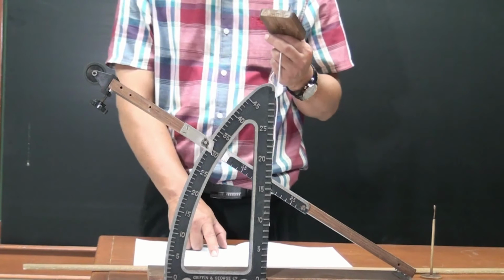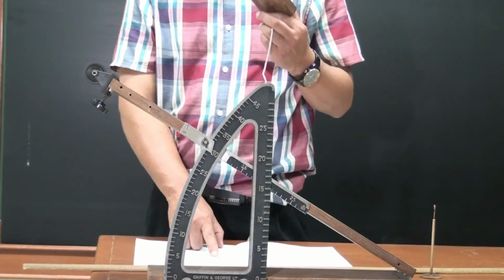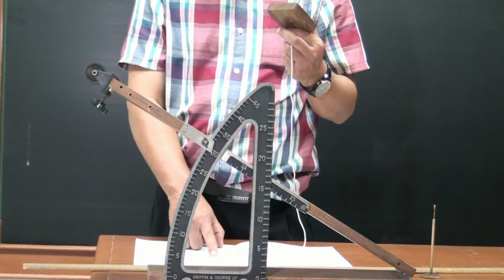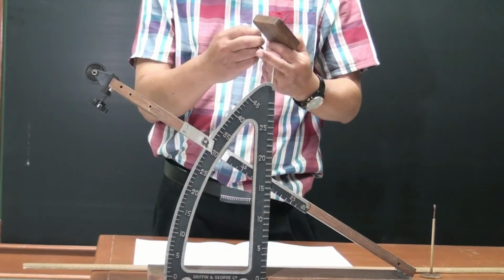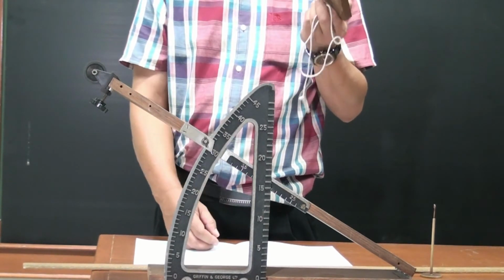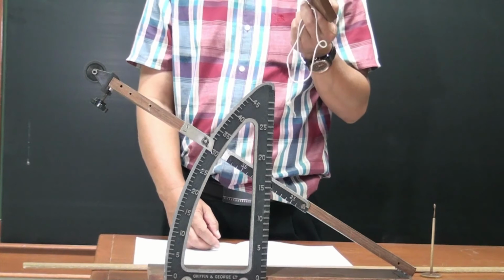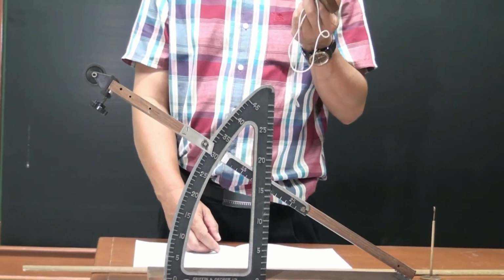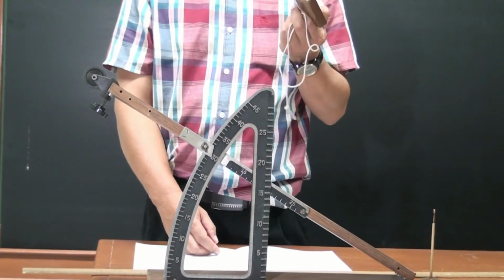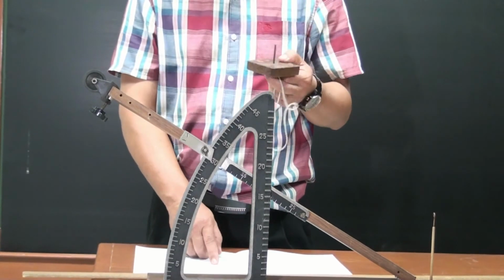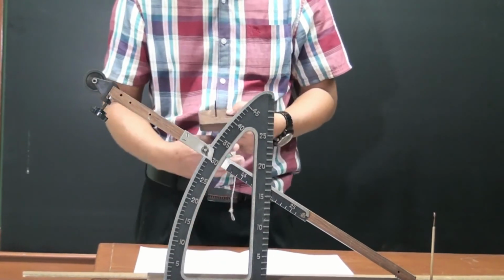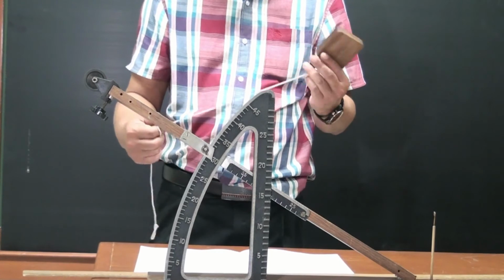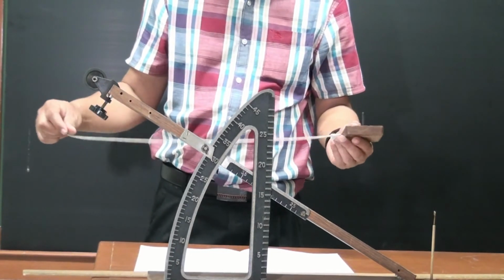Once you have the velocity ratio calculated, you can start putting this little piece of slab on top of your inclined plane. This piece of slab is going to be your cart that you're going to be pushing upward onto the inclined plane. So whatever weight is being put on here is going to be your W in the equation, and this is the material that we're going to be making work in order to get it across the inclined plane.